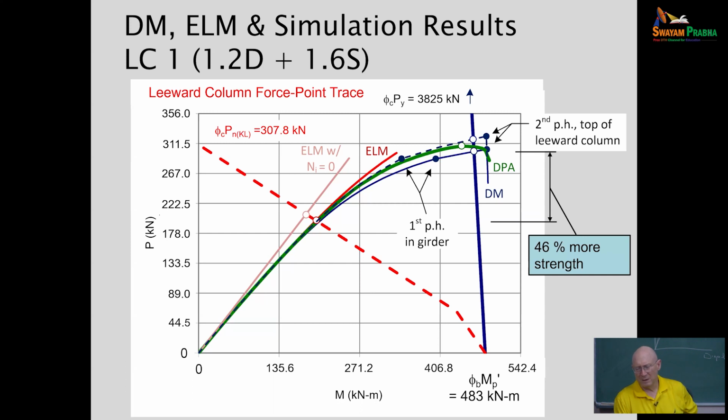And if we did this more in the form of the way Eurocode would do it, rather than having a stiffness reduction, here it's a 0.8 stiffness reduction on all the elastic stiffnesses, the Eurocode would use a larger notional lateral load, and so that would tend to give larger lateral moment. If everything is working perfectly, we get about the same result either way.